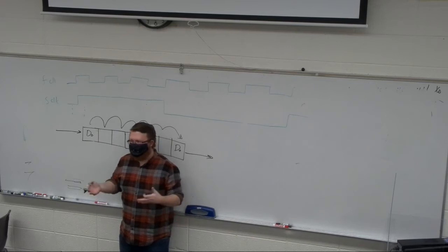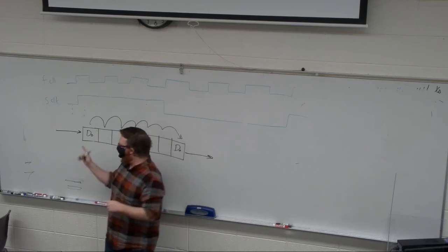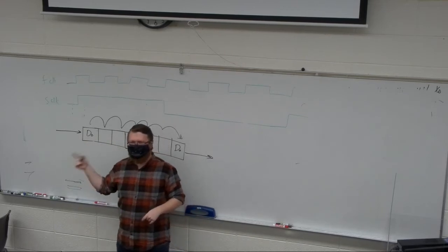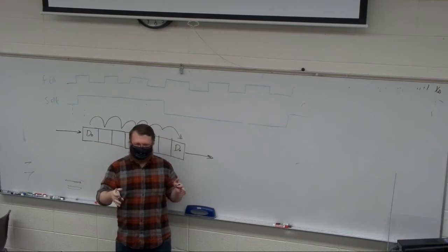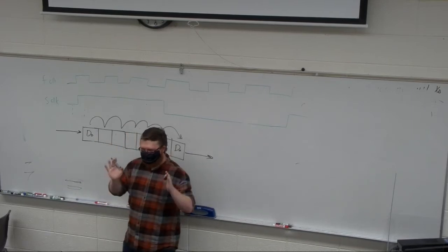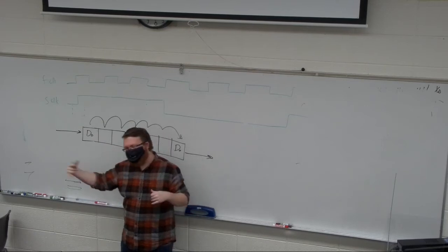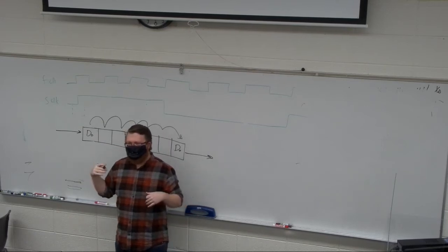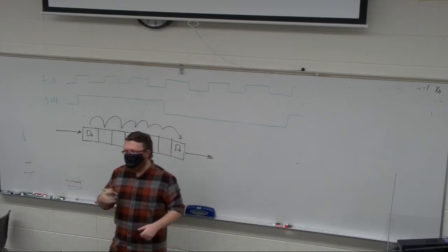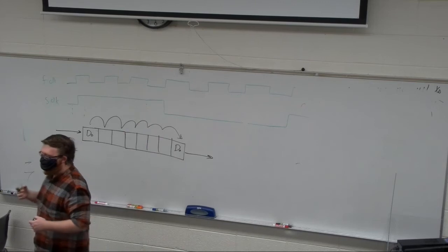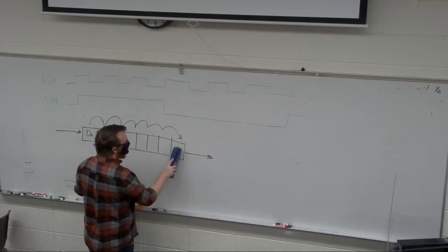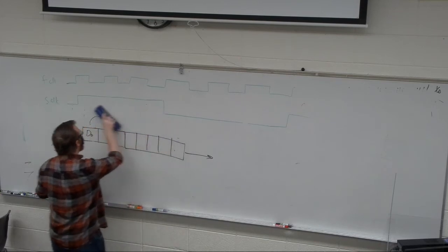Or I can fill it in with bad data, or I can fill it in with essentially don't cares, right? But I have to keep track of that. So anytime I pause for any amount of time while I'm still shifting, I now get dead zones where I have to shift out that unwanted data, and that can cause delays throughout the program. So it's not just a startup problem. So the answer to this is instead of using a shift register, we use a FIFO.